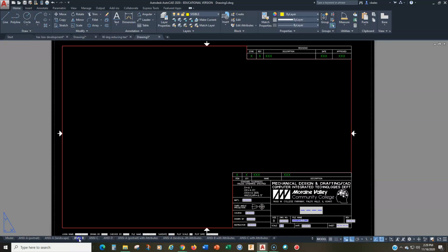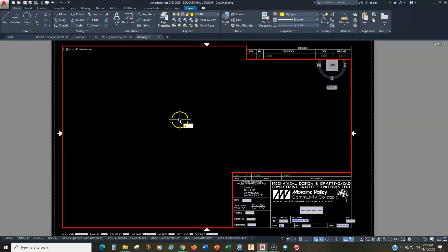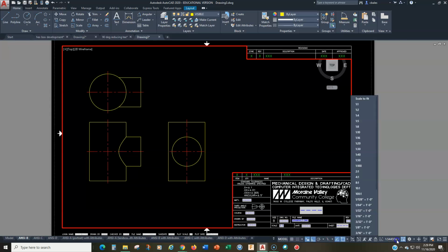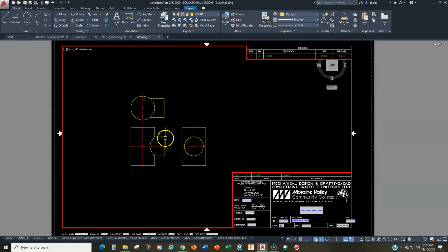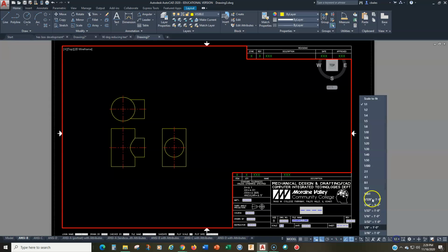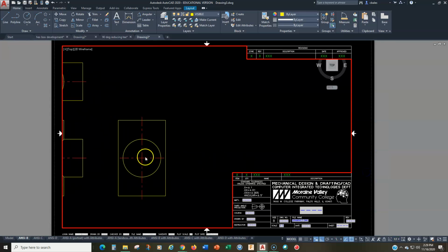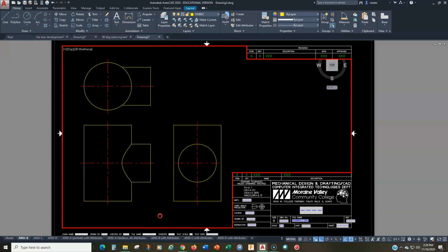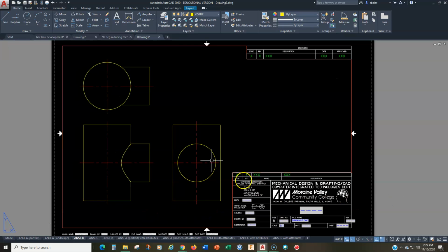And then we go to the B-size sheet, and we double click in here. We do zoom extents. We're not dimensioning this, so we're just going to come in here and we'll set this at, will 1-to-1 fit? Nah, 1-to-1, boy, that's a little bit small. Can we get 2-to-1? Hey, what do you know? We can get 2-to-1. I can move this in a little bit more. Just a smidge right there. And there we go. So there is your solution to CAD exercise 8.2, the reducing T.